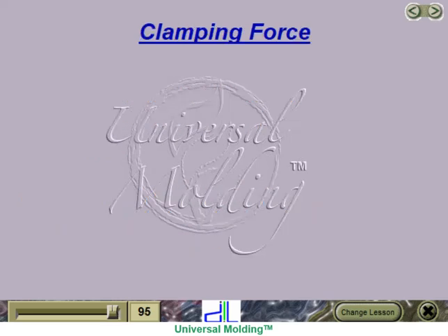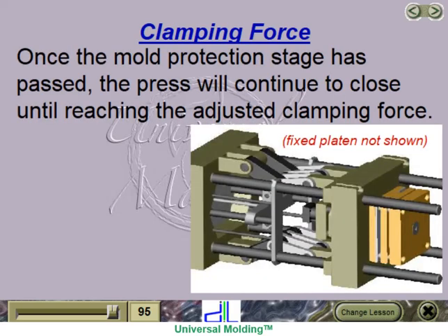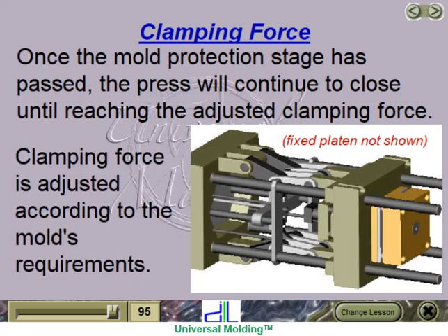Clamping force. Once the mold protection stage has passed, the press will continue to close until reaching the adjusted clamping force. Clamping force is adjusted according to the mold's requirements.